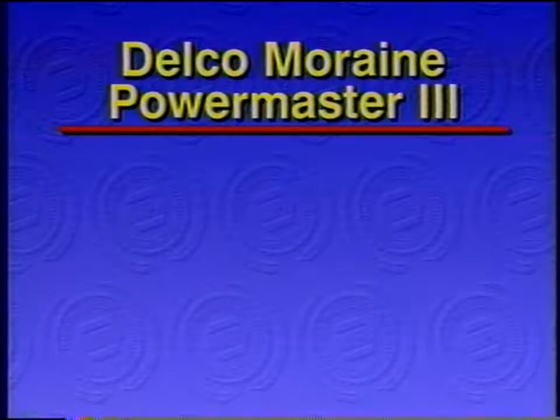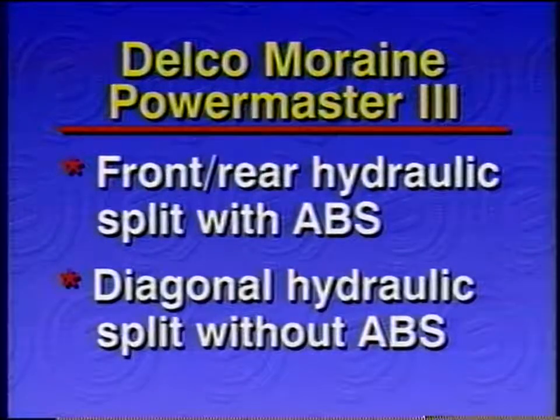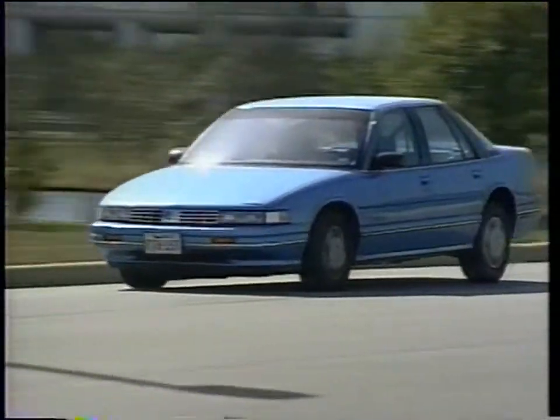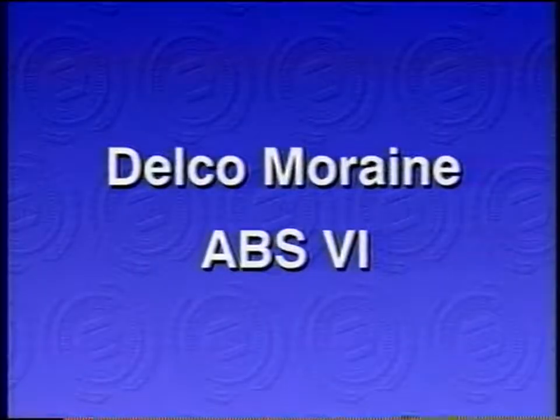An interesting point to note about the brake system on the cars where the PowerMaster 3 system is offered as an option rather than as standard equipment is the way in which the brake hydraulics are split. On cars with this ABS system, the primary and secondary sides of the brake system are split front and rear, while those that do not have ABS are split diagonally. Now, the PowerMaster 3 system itself is a 3-circuit system. The front brakes are controlled individually, but the rear brakes are controlled as a pair.